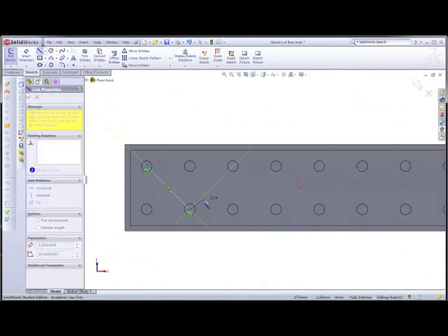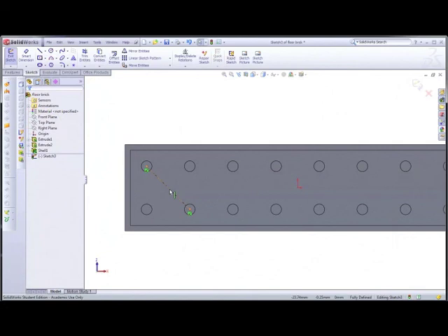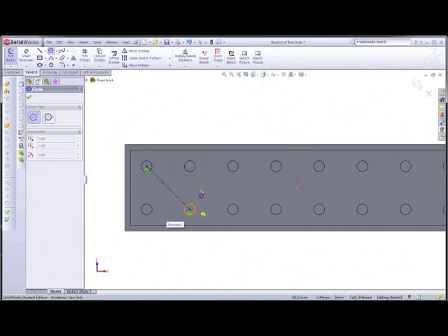So you want to click between the two centres, so therefore we have a centre line created. And I'm using this centre line as a reference for me, guys. So it's really important. Get into the habit of using the centre lines.